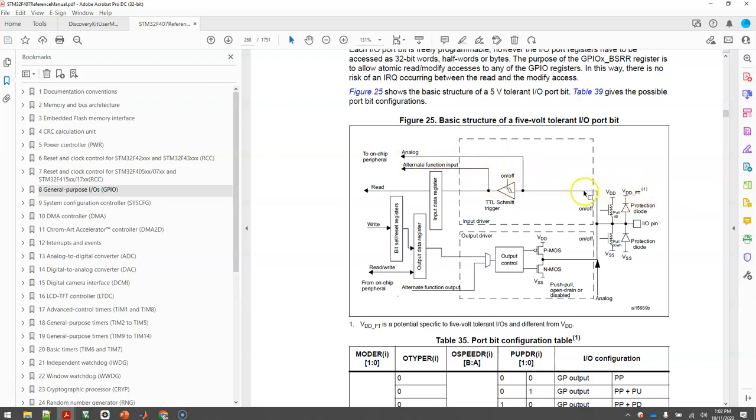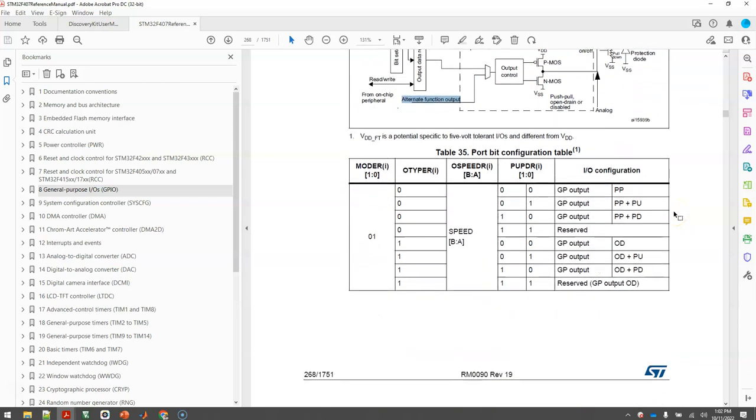You can also use the input coming in from the pin to do some alternate function. Instead of sending data to the input data register, you can set up that pin to be an alternate function input and grab that towards additional internal peripherals or internal registers like UART, SPI, and so forth. Similarly, you can push data from the chip to the output pin through the alternate function output mode. Instead of the output data register, which we've been writing to, we can set up that pin as an alternate function output. So alternate function output can be done by setting this multiplexer to a certain value and then basically moving out. How do you select that multiplexer?